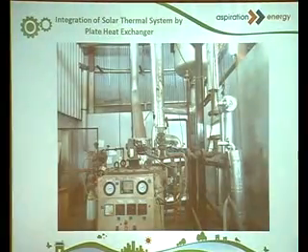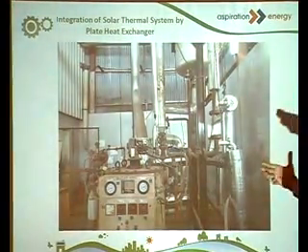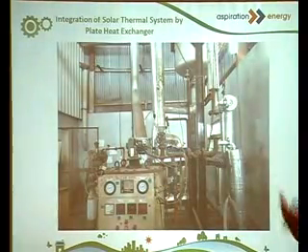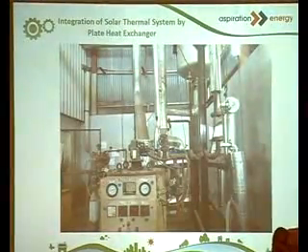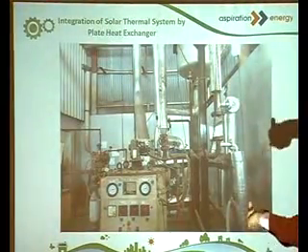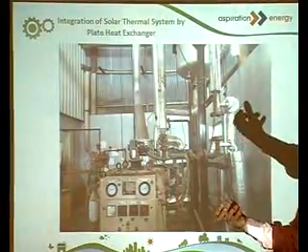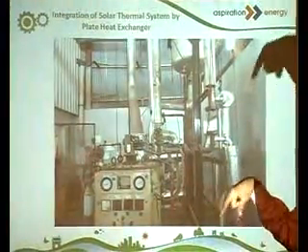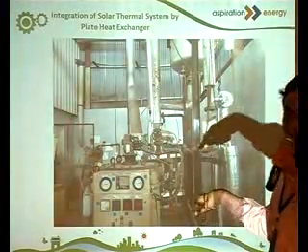So that's an external plate type heat exchanger, PHE, and this is slightly more complicated than inserting the coil directly into the tank, because in this case you are taking dirty fluid from inside the tank and heating it up. So filtering and putting it back becomes an issue, and you're introducing a new pump here.